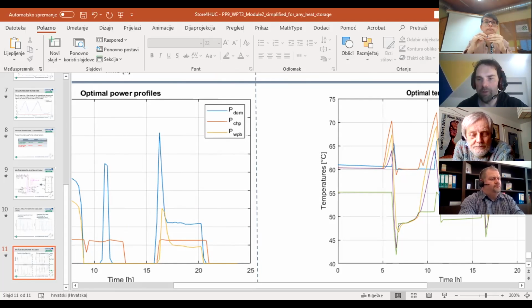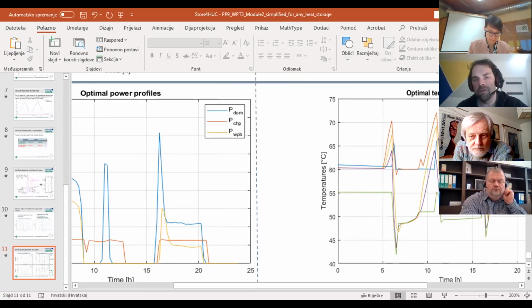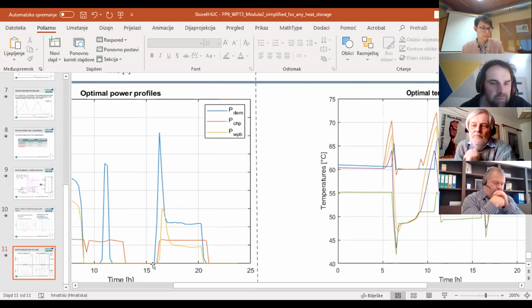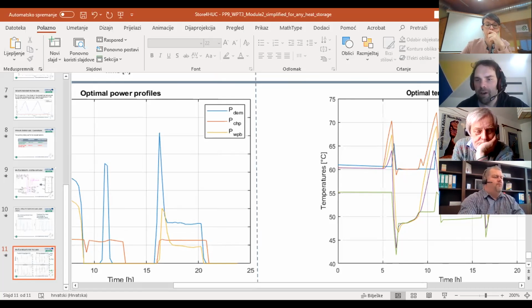And in this period, let's say from 12 to 16, because the water is not used, the temperature has risen and has equalized with the highest temperatures in the tank, then you cannot use CHP. And for instance, when the load here rises again at 16, you first wait for things to cool down a bit in level 4, and then you again plan to engage your CHP.